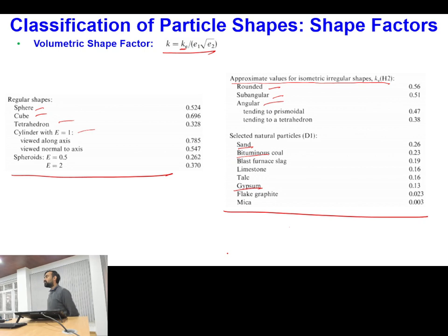Okay. So by using these tables and doing the basic length calculation of the particle, we can calculate the values of shape factor. And how will shape factor be useful? Whatever relation of interaction forces is applicable for a spherical particle, the same relation can be applied for complex shapes, non-spherical particles, by just using the multiplication of the shape factor. So that will be coming as a multiplier.